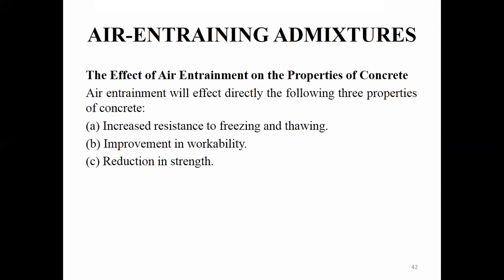Having fulfilled the requirement of workability for placing and compaction, the extra air will escape, or may be made to escape, to achieve the desired density in the hardened concrete. See, in conventional concrete, what happens? There will be some amount of air voids that can be filled by the cement paste to get the desired workability. Similarly, in air entrained concrete, you will get more air voids, so you will require more cement paste, right?